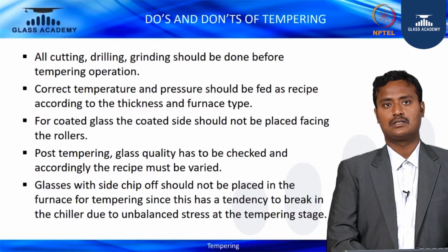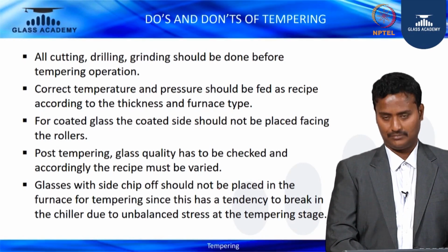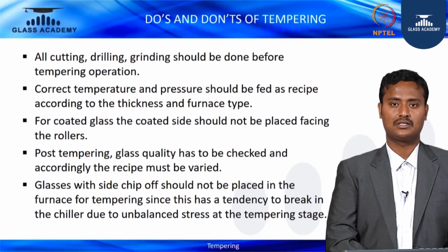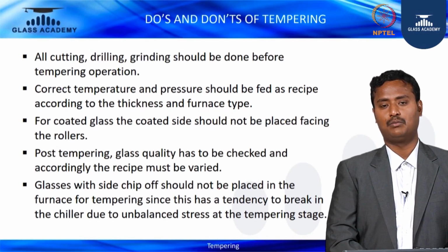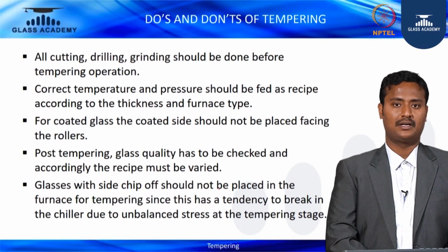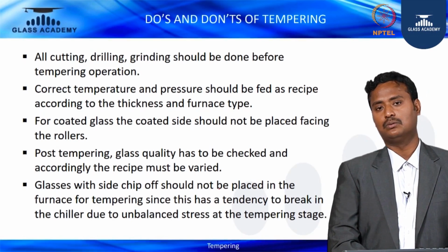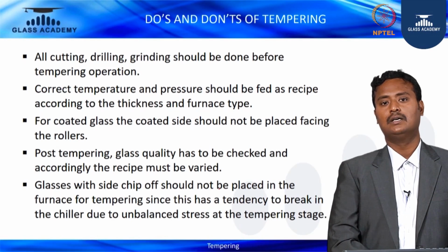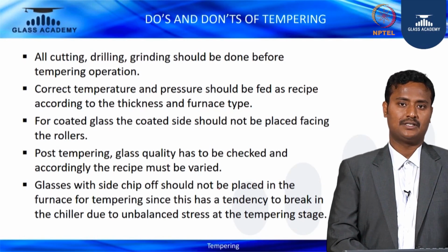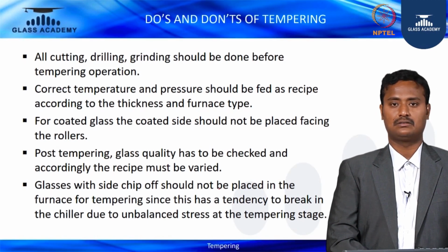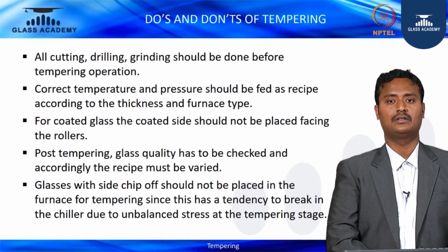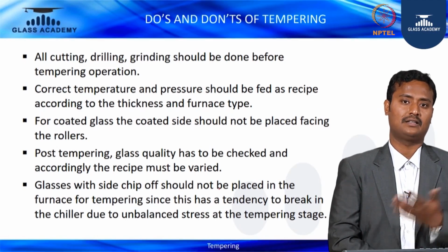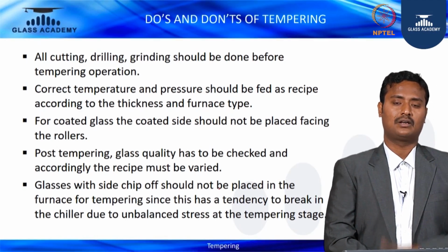For coated glasses, the coated side should not be placed on the roller face, because the coating would be damaged and the rollers get damaged. When the coating goes away, you will have more scratches and the performance would not be obtained from these coated surfaces. So at all times, from the crate opening, which means cutting, pre-processing like grinding, washing, drilling, and tempering, all coated products should always be fed with the coated side facing up on the air side. Basically, it should not be in contact with the rollers.